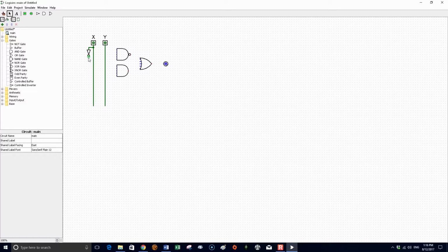When you're creating wires, you can only put one bend in it per drag, but what I can do is drag it part way and then drag some more. As long as I let go part way through, I can put those wires exactly where I want them. This is more important than it might seem at first glance, because if you just let the wires do whatever they will, you end up with them running into other pins, and then your logic circuit won't work at all. So this is a pretty typical setup when we are translating a truth table to a circuit, usually with something like sum of products.